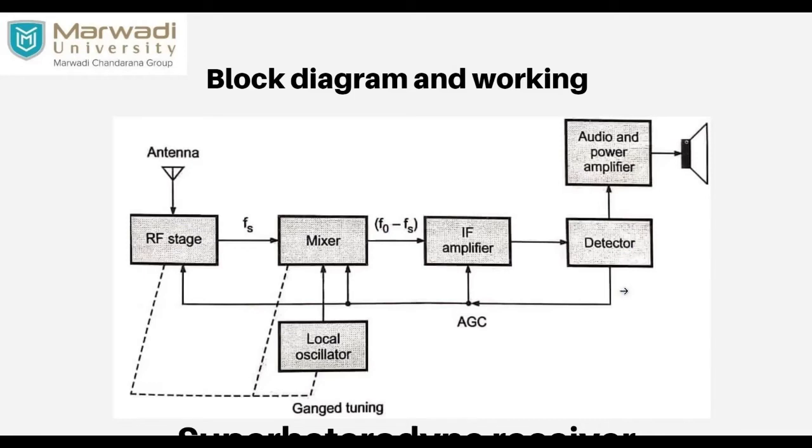So this is how a superheterodyne receiver works, and from this we can also deal with high values of frequencies, because from the mixer we can pass only some values, and from the local oscillator we are able to generate frequencies of our choice.